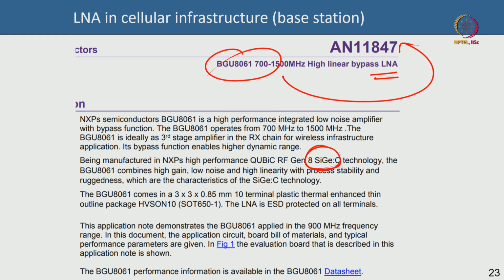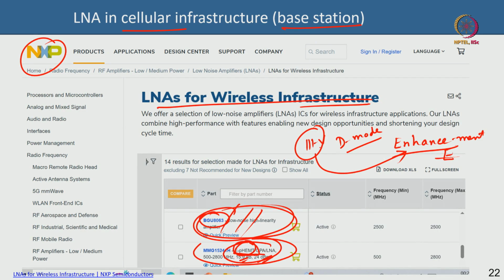So, silicon germanium bipolar technology is used in cell phone towers as well as in radars, maybe cell phones, whereas gallium arsenide based HBTs are used in power amplifiers in your handphone. In the cell phone base station tower LNA, low noise amplifier, people also use gallium arsenide HEMT. Please remember that. Okay, they also use gallium arsenide HEMTs.